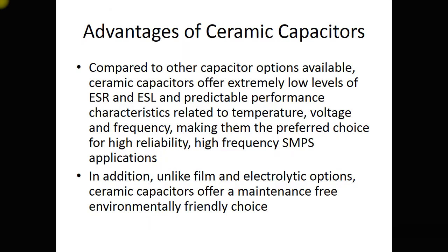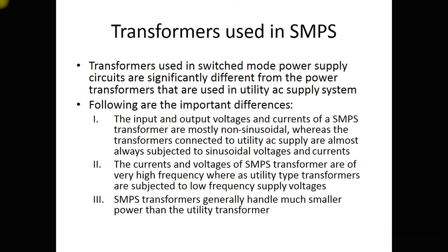The advantages of ceramic capacitors compared to other capacitor options: ceramic capacitors offer extremely low levels of ESR and ESL, and they have predictable performance. Characteristics related to temperature, voltage and frequency make them the preferred choice, especially where you require high reliability, given the high frequency application in SMPS designs. In addition, unlike film and electrolytic options, ceramic capacitors offer a maintenance-free, environmentally friendly choice. So this is again a very important issue, especially from the environmentally friendly design approach.